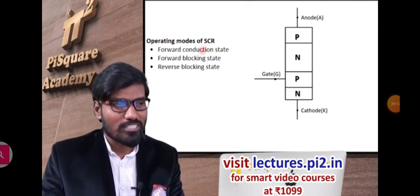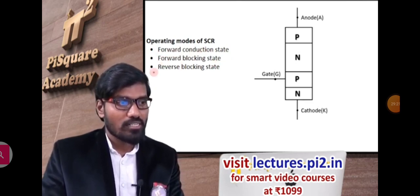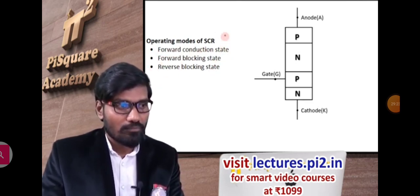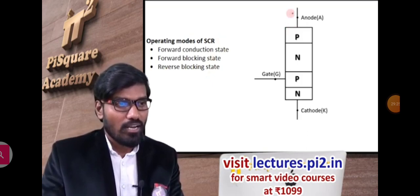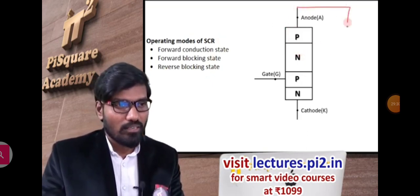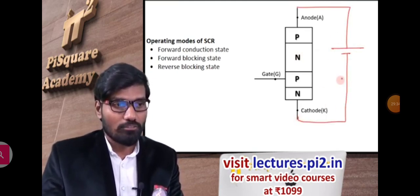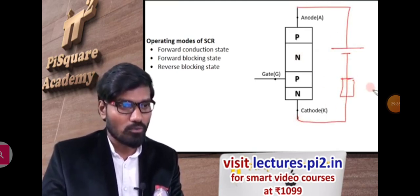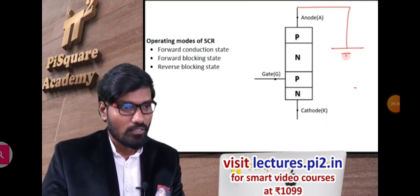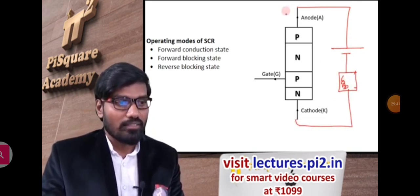What are the operating modes of an SCR? Forward conduction state, forward blocking state, reverse blocking state. They are the operating modes of an SCR. And this is the SCR's basic schematic diagram. We'll normally have a forward voltage through some load. I should draw that also, otherwise it will be a short circuit. Yes, this is a load, and it's applied like this.